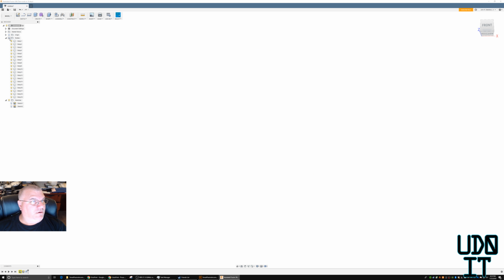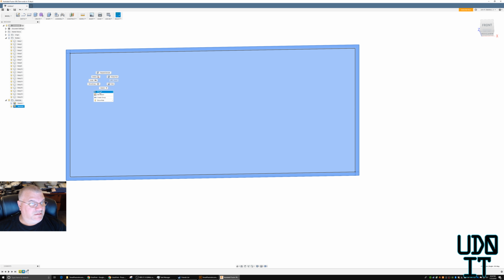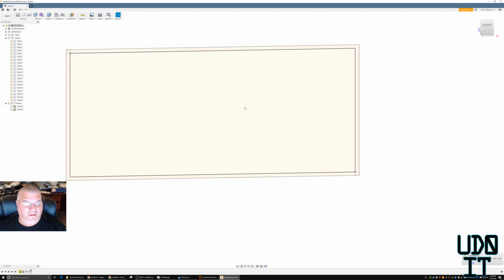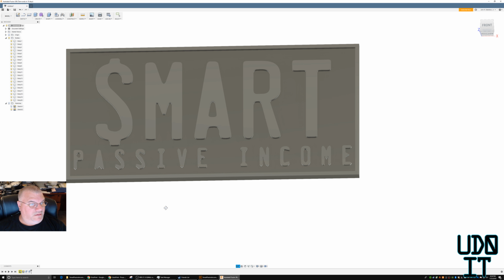But right now I'm going to turn off the bodies. I'll turn off that sketch. I'm only going to have this sketch on, and I want to select these two regions, and I want to extrude -3mm. And I'll show you why I want to do -3. And that just created my other body. So let's turn sketches off, and let's turn the body on.